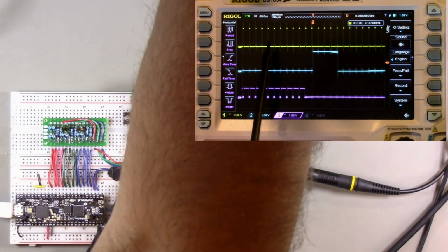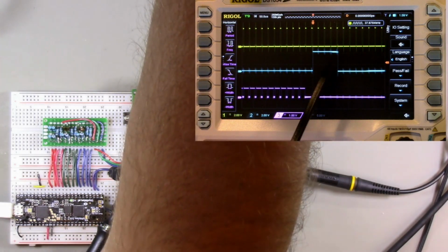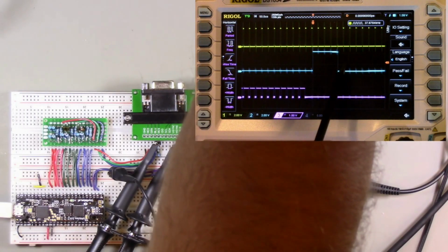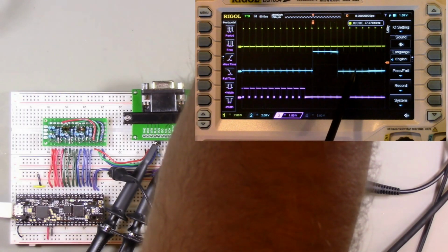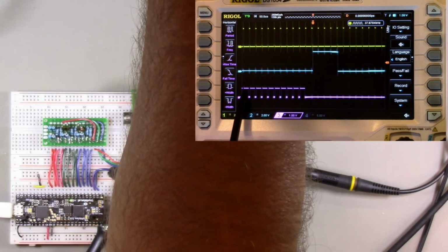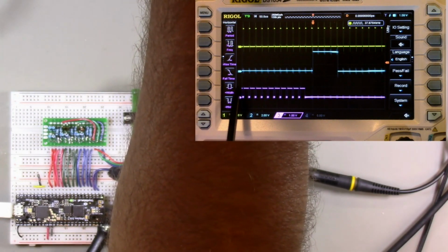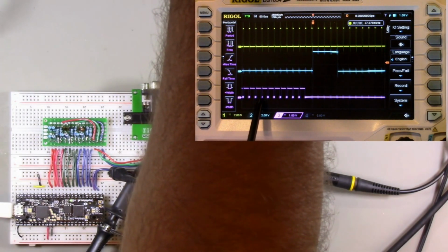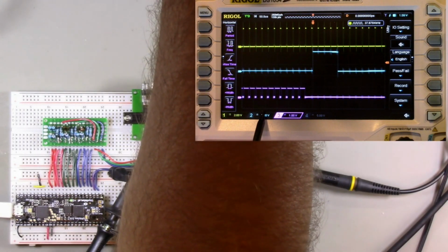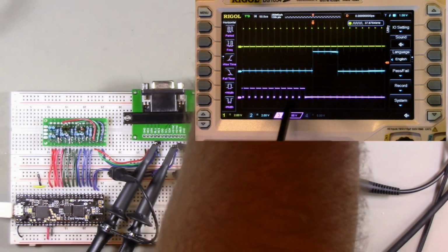And so here are the horizontal sync pulses, and obviously they occur much more frequently than vertical sync. So here is the front porch and the vertical sync, and the back porch for the vertical sync. And as you can see, when we generate these color voltages, we are only generating a positive voltage at points where we are in a visible region. So for example, here, these dots where we have 0 volts, those correspond to horizontal sync pulses, and of course the front porch and back porch of the horizontal sync being generated.